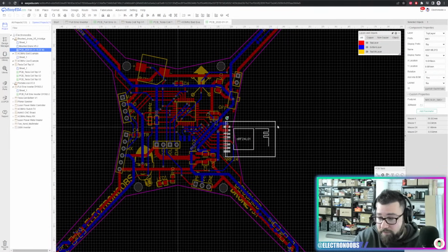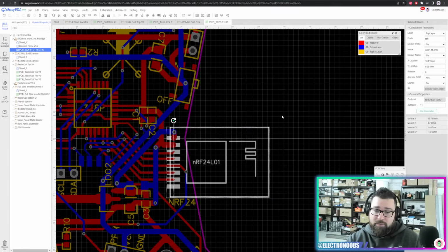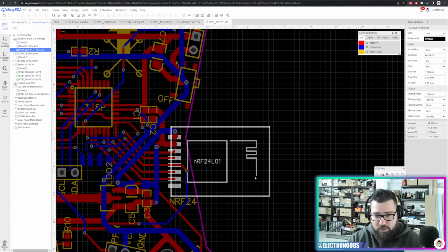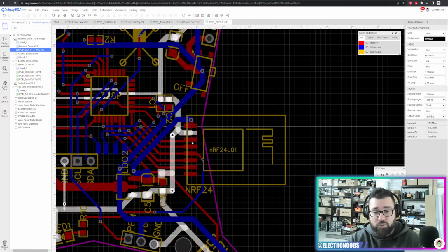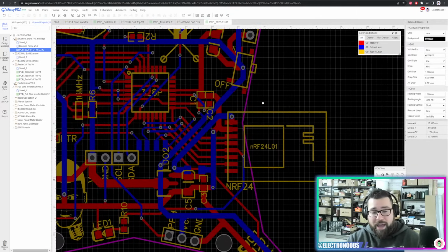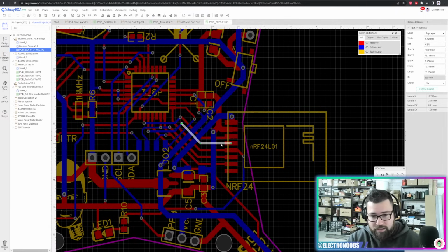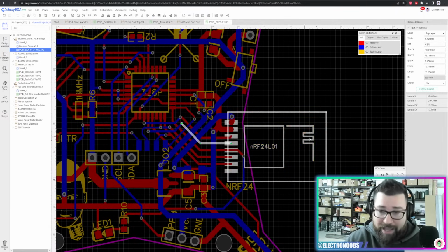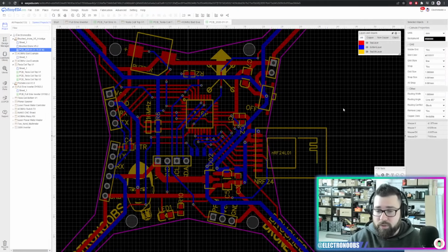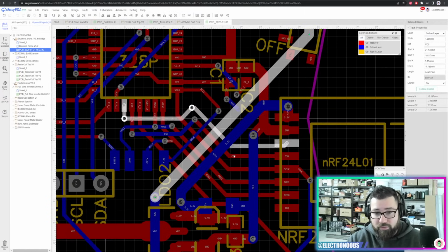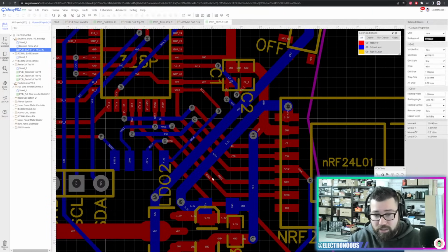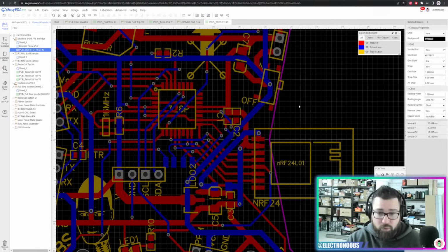Another problem that I found is the difference between the noise of the radio antenna and the noise between the connection and the microcontroller, the SPI connection. So I had a lot of noise on these tracks that are using digital communication, and not noise on the antenna. So I was receiving the signal okay, but the signal getting out from the module had a lot of noise. For example, these tracks are power tracks and are overlapping with the SPI tracks, which are this one here, and they were creating a lot of noise.